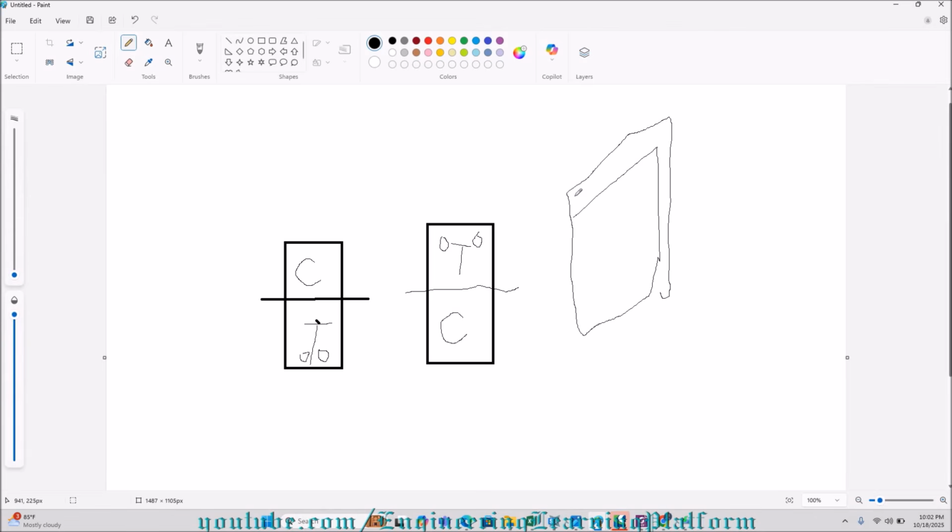The code recommends using 2 layers for walls greater than 10 inches thick. However, we also use them even if we have an 8-inch thick wall, as in our case, because it will serve my purpose.